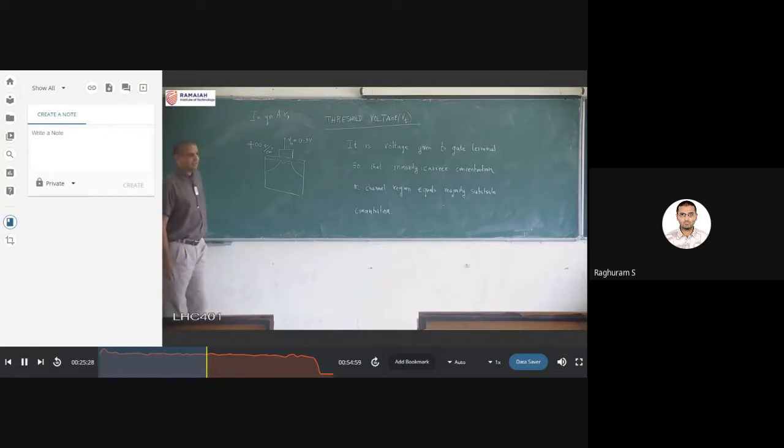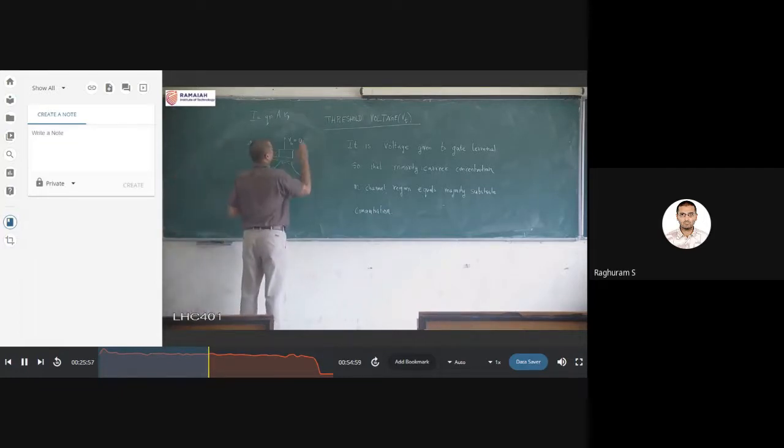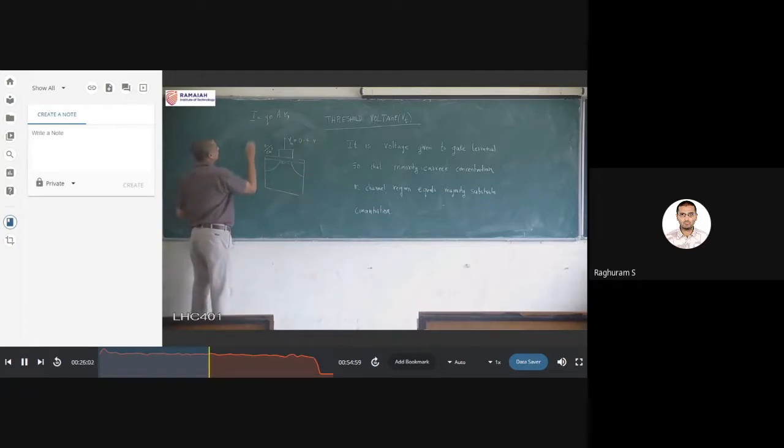the single transistor current, that is the current flowing through a single transistor when it is on, might be in the milli or microampere range, because it's one transistor. It's a very small value. But here, if I use this equation, I am getting 10 power minus 15. That is a useless current. So this value of Vg is still not enough. Let me increase it more, and say I go to 0.4. Now suddenly this might jump from 400 to 4 e power 6, and this is definitely higher.